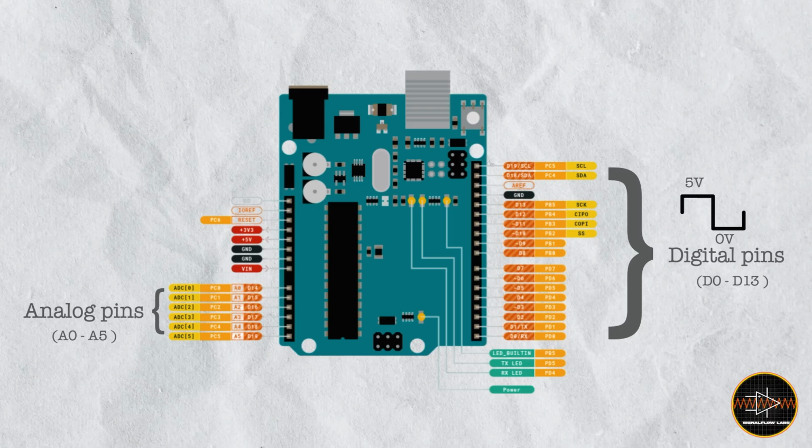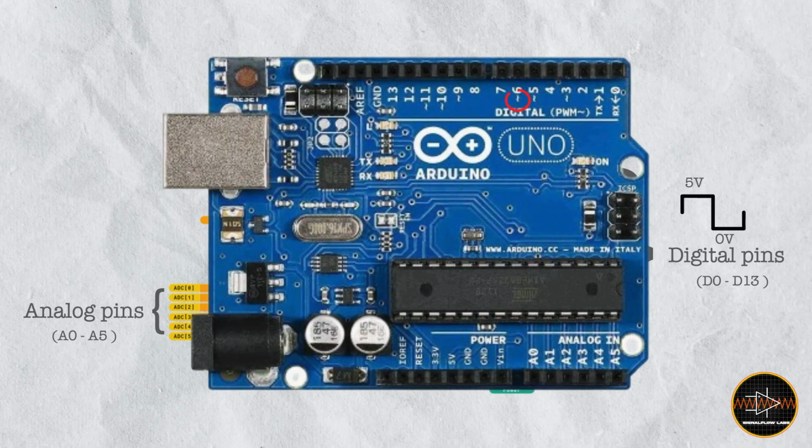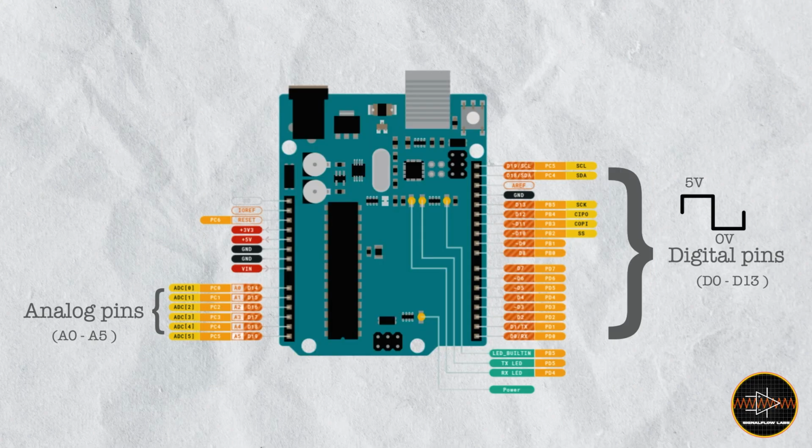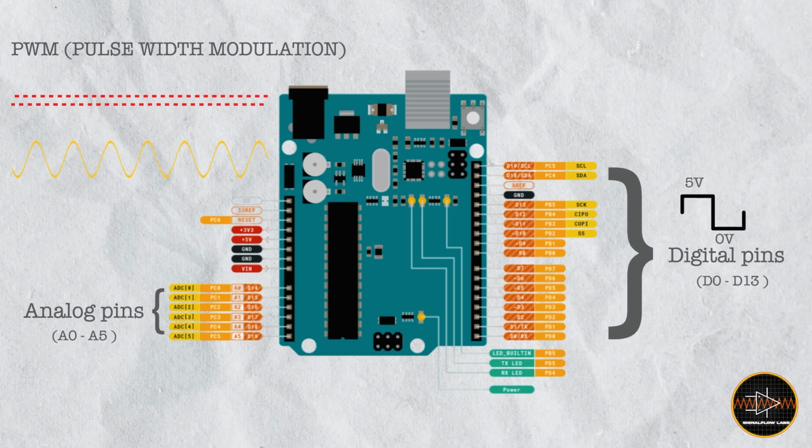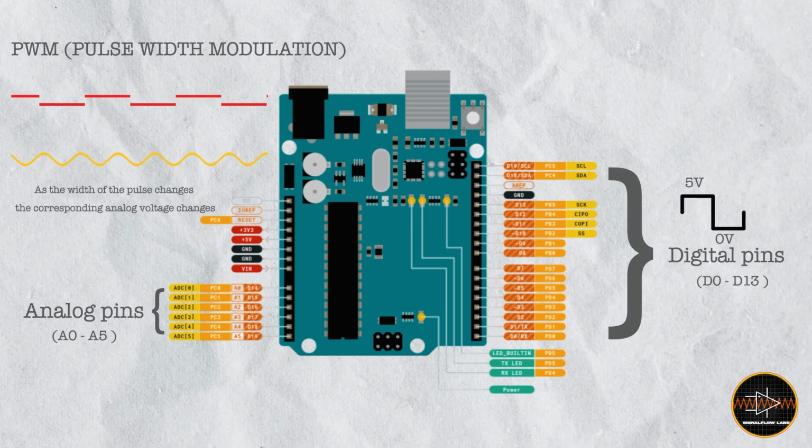On those pins, there are certain marks you can see on the screen. Just mind the mark that is used for PWM. All the pins in Arduino Uno can't use PWM. What PWM stands for is, if I want to give an analog value to a sensor, light, or bright LED, then at that point I have to vary the width of the wave of the digital pin, so I can vary that voltage. So it's basically high frequency output that comes into the picture. If you can see on the screen, that's visible, and in that way you can manage it.